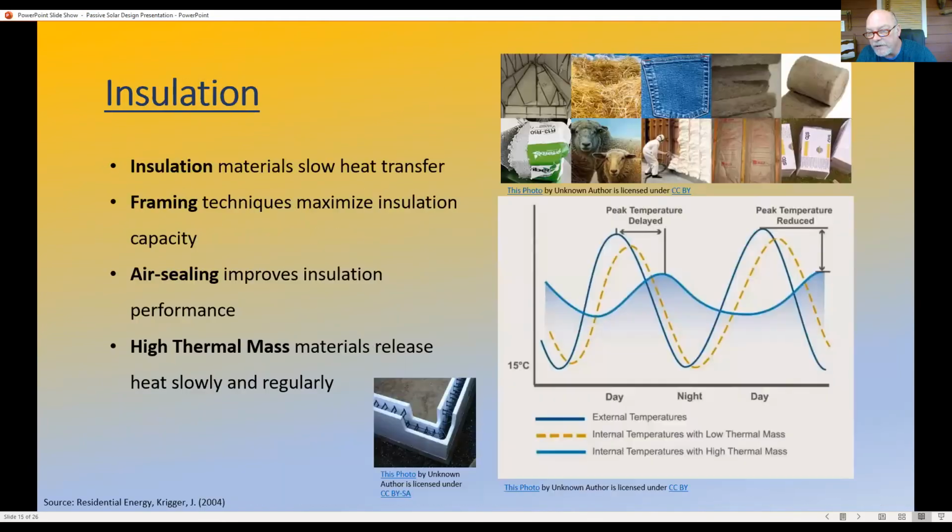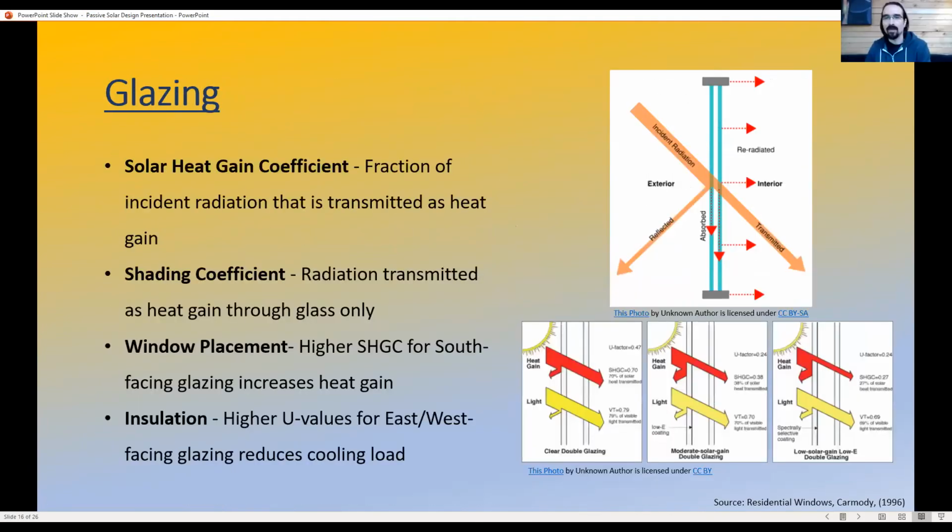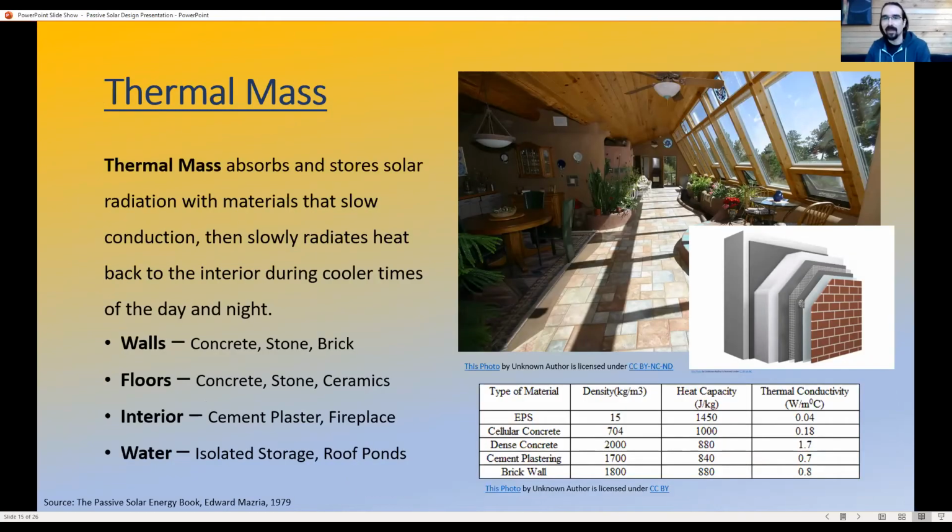Also notice the vegetation in that room. Sure, yeah. My first experience with this sort of thing was an indirect system that was a greenhouse outside. And in that situation, you also have to be very careful about your moisture transfer, because you end up with a lot of moisture in a greenhouse that you might not want to bring into the space. So if you're using an indirect system like a greenhouse, you might not want to use a vented system necessarily, or you might want to have other means of controlling moisture entering the space.